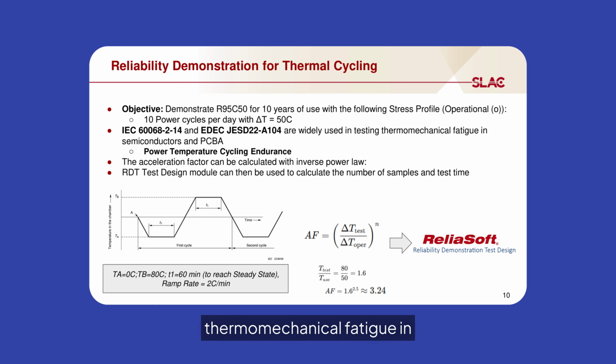To evaluate thermomechanical fatigue in semiconductor devices and PCB assemblies, industry standard test methods such as IEC 60068-2-14 and JEDEC JESD22-A104 are commonly used. These standards define power and temperature cycling endurance tests that are designed to accelerate fatigue damage while preserving the underlying failure physics.